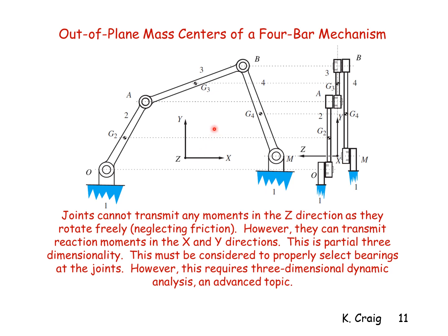However, when you build this and look at its side view, you see that all of the links cannot be in the same plane of motion because they'll bang into each other. They need to be separated by bearings with short axles that cause the system to look like this. So from the side view, there is no identifiable plane of motion.